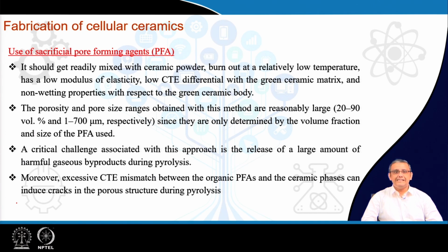If the pore forming agent is not distributed in a uniform manner, then again we have a non-homogeneous pore structure, which might lead to poor properties in the final porous ceramic. And the second problem is that, as with the gel casting process, while using polymer pore forming agents, the burning and pyrolysis of the polymer can give rise to harmful gases, which are harmful for the environment and also for the operator.